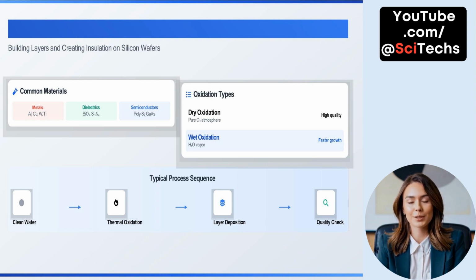Common materials, oxidation types, and process sequence. In semiconductor fabrication, a variety of materials are used to build the layers of a device. Common materials include metals like aluminum, Al, copper, Cu, tungsten, W, and titanium, Ti, which are used for electrical conductivity. Dielectrics, such as silicon dioxide, SiO2, and silicon nitride, Si3N4, serve as insulating layers. Semiconductors like polycrystalline silicon, poly-Si, and gallium arsenide, GaAs, are used for active electronic behavior.